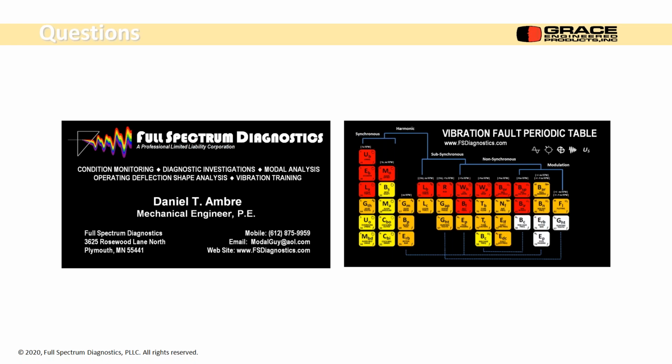It could be a little problem getting bearing defects to show up because they're pretty subtle, but for any other threshold type thing, the synchronous vibration, the harmonics, blade passing, things like that, electrical frequencies, you'll see a good trend developing for those. The bearings are a little harder. That's why you need a separate measurement of ultrasonic energy.